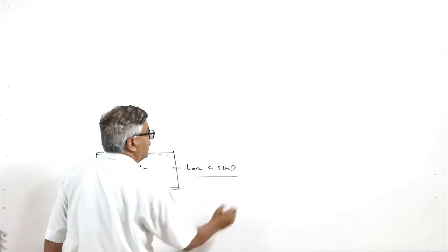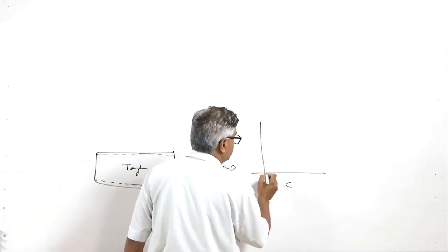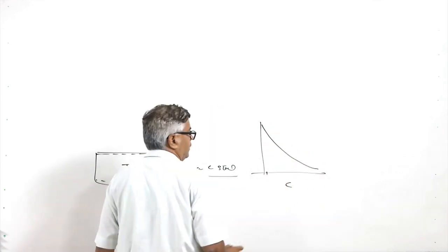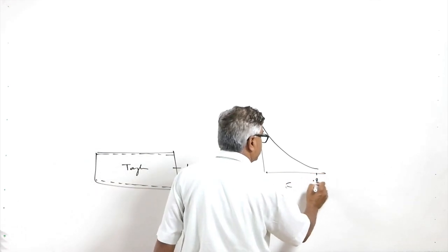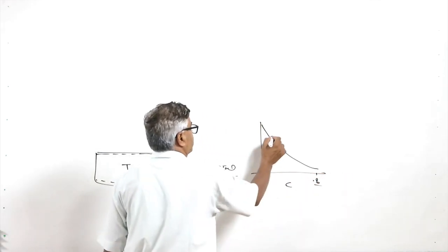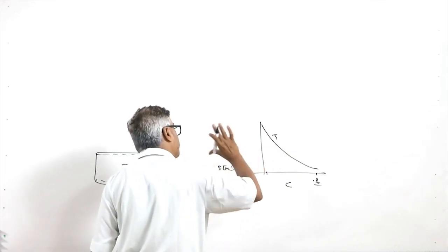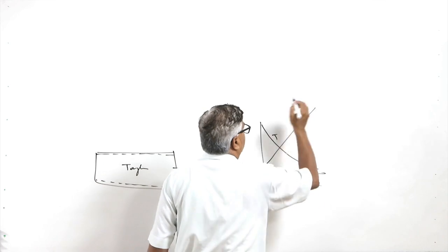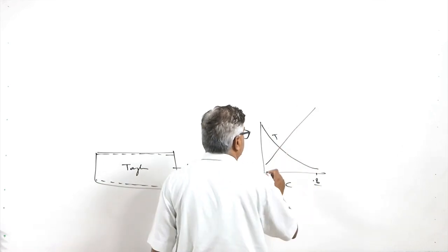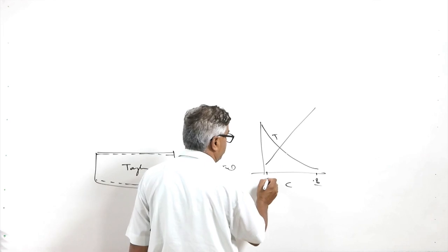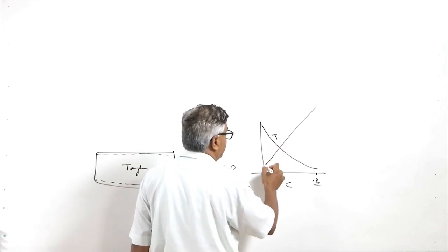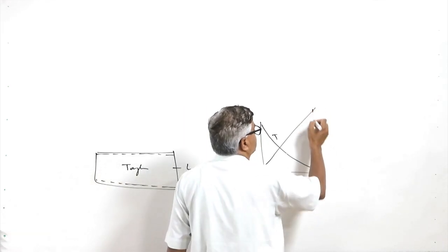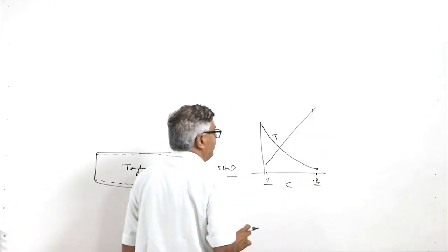Low carbon steels, as we see in this diagram, carbon content low carbon, so it will be offering you higher toughness, and with the increase of the carbon content, there is a reduction in the toughness value. While in terms of the hardness, there is continuous improvement in the hardness. So, when the carbon is low, say 0.1, the toughness is high but the hardness is very low. When the carbon is high, the hardness is high but the toughness is very low.